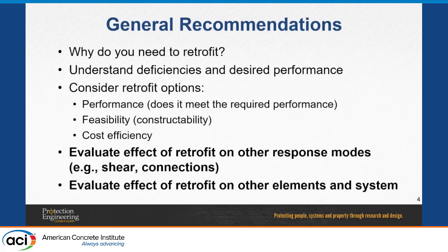For example, if it's shotcrete and you're adding concrete, then you might be increasing the weight. So now what about your foundation? Can your foundation take that? So you have to, again, not just think of that element, but the effect of retrofitting that element on other elements.